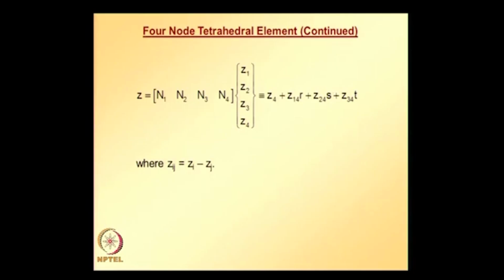So, we can easily take partial derivative of x with respect to RST, y with respect to RST, z with respect to RST, and we already know how to calculate derivatives of displacement components with respect to RST. So, using both these pieces of information and the chain rule of differentiation, we can easily arrive at derivatives of displacement components with respect to x, y, z.